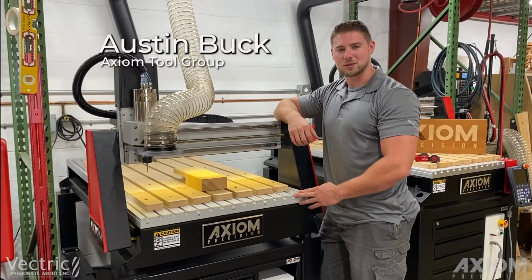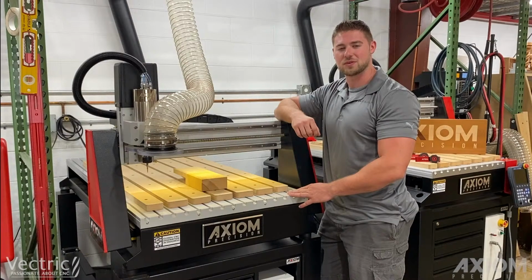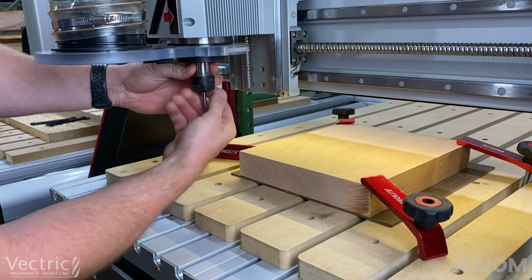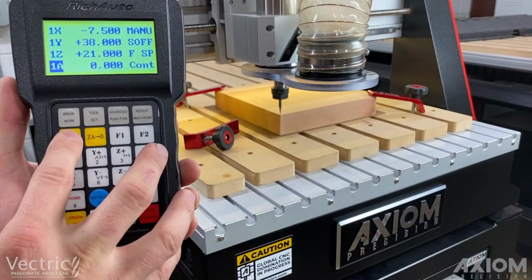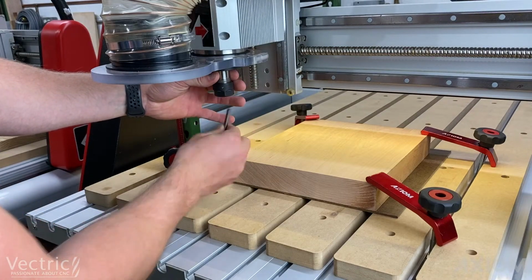Hi everyone, my name is Austin with Axiom Tool Group, and today we're going to show you a unique 3D model cut in our Axiom Pro V5 series machine. Alright, so the first thing that we're going to do is insert a V-bit into our machine. We're going to use this to set up our XY0 position, or that origin position. So once that's been set in the control, we're going to remove that bit.